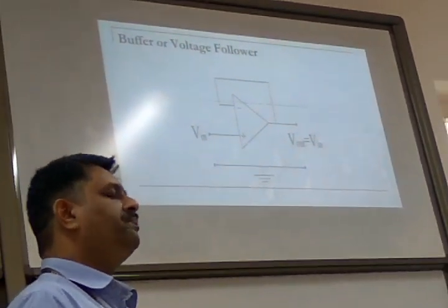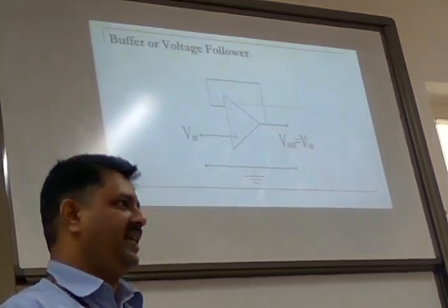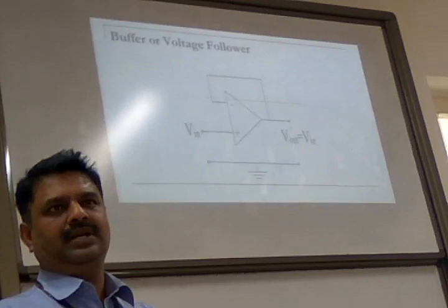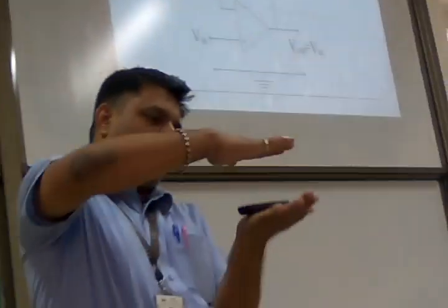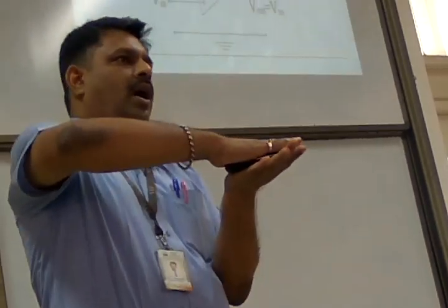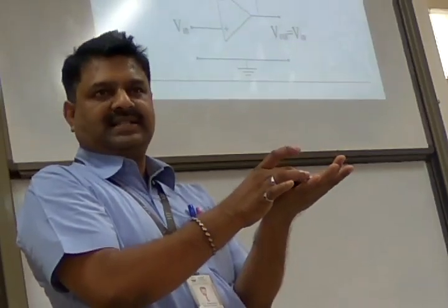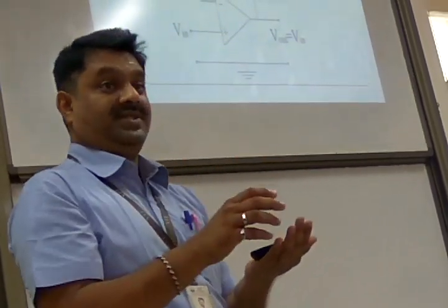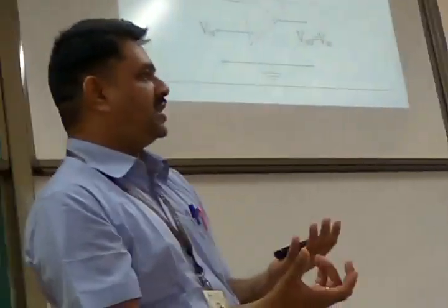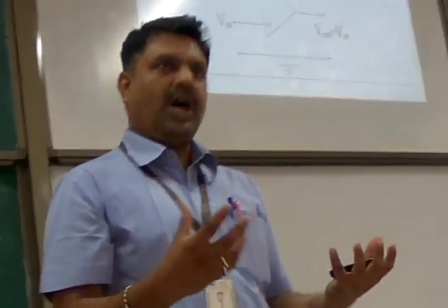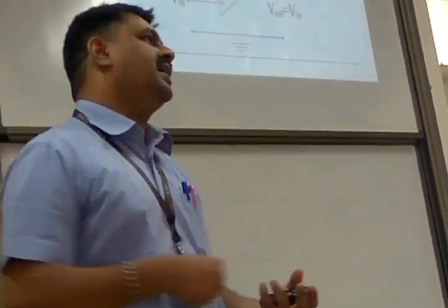For example, we have learned the piezoelectric accelerometer. You remember the piezoelectric principle? What is that? If you have a piezoelectric crystal and you apply force on 2 parallel sides of it, charges are developed on the other 2 parallel sides. It is only charges. It is not even voltage. Some positive charge on one side and some negative charge on the other side. If the charges are more, that you call a potential difference, and there will be a current flow.